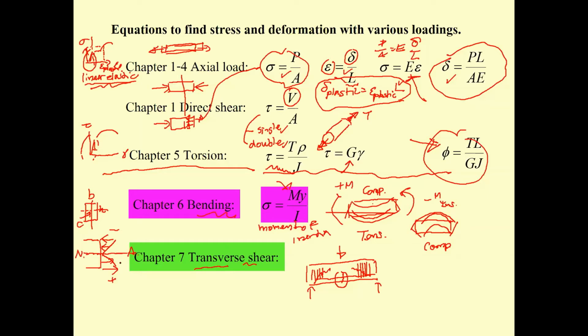That is the axis that has no stress. And then you will see the effect of y here. If you put this one as 0 and up is y, if y increases, the stress also increases linearly. This distribution is in triangular shape. And the moment of inertia over here is going to be BH cubed divided by 12.